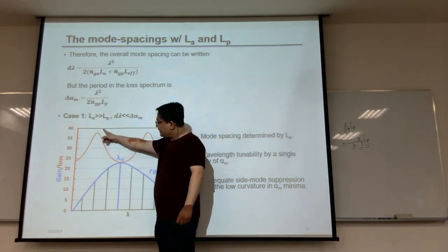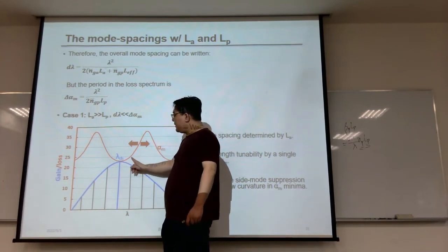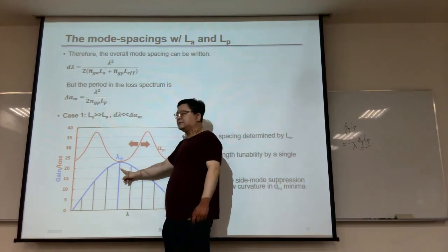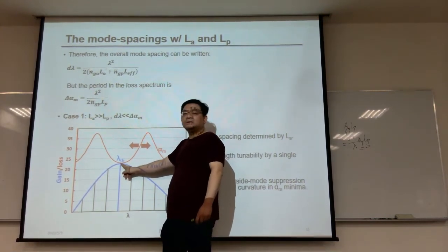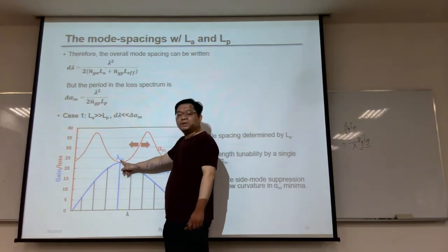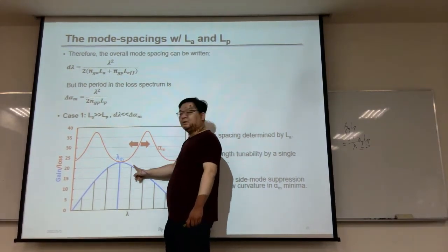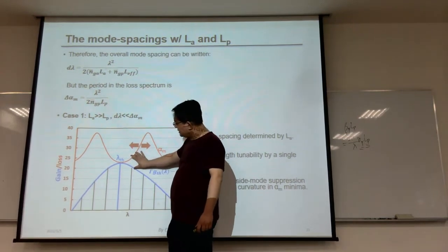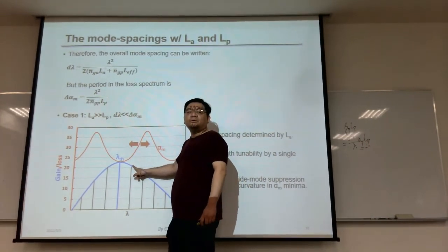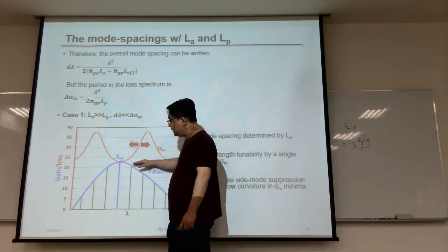But since we have a variation in the loss spectrum, when the gain increases, maybe one of them, the lowest point, might be getting close to its modal gain minus internal loss. So while this reaches the criterion of lasing, for its side mode, the distance between lasing and the actual real gain is higher than the case with a uniform loss.